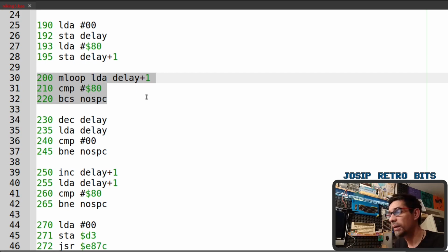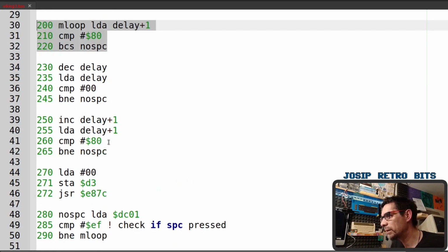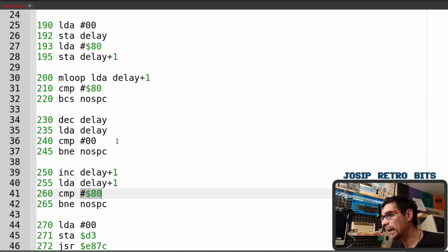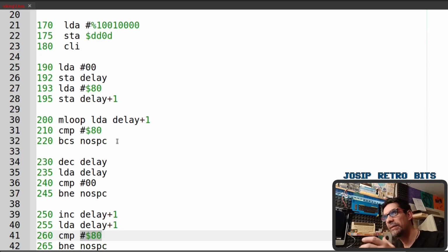And it will happen in the interrupt routine. So in the interrupt routine, once we receive the signal, we will start our counter, so we will reset it to 0. It will begin to count, and it will try to go all the way up to 8000 hex. And every time we receive a new signal, that means every time our interrupt routine is activated, we will reset this timer.